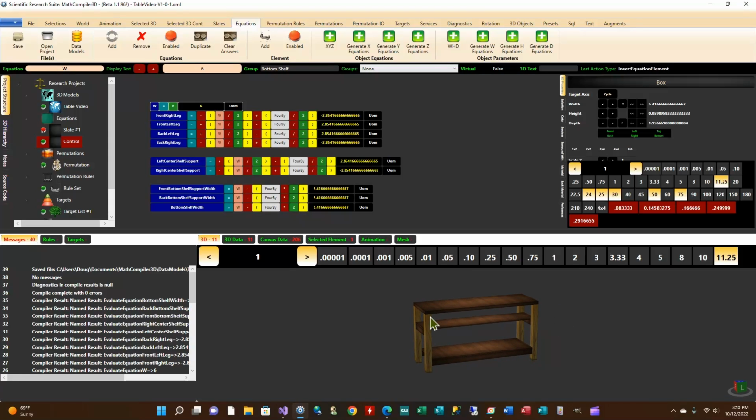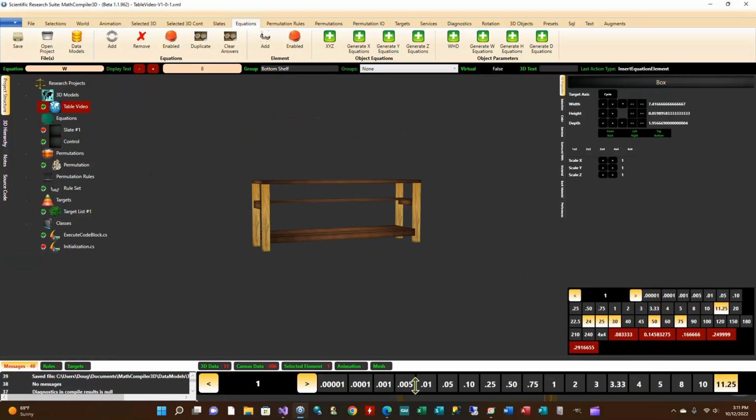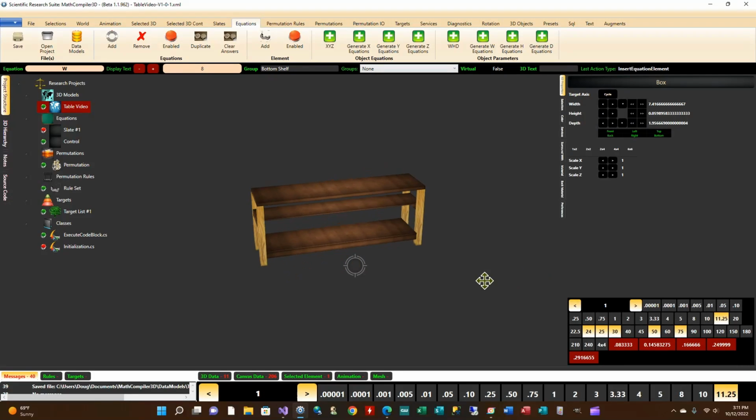So now if you wanted a long shelf in your shop in order to store tools, then you can make this up to 8 feet long, hit F6, dynamically compile, and there you go. Now, with it being 8 feet long, you may need a center support for your shelf because at some point 3/4 inch plywood will get a little bit weaker, but if you're just placing light things on, then you're good to go. But nevertheless, the whole point is to make this formula highly reusable. And there we are, a nice parametric formula.